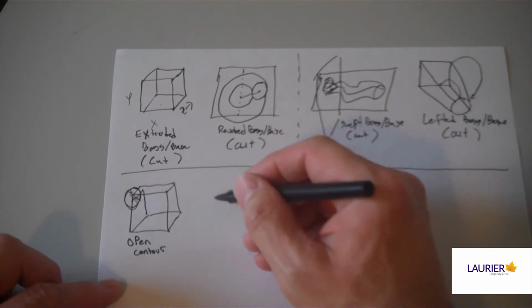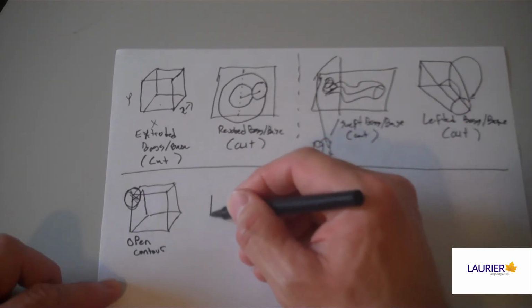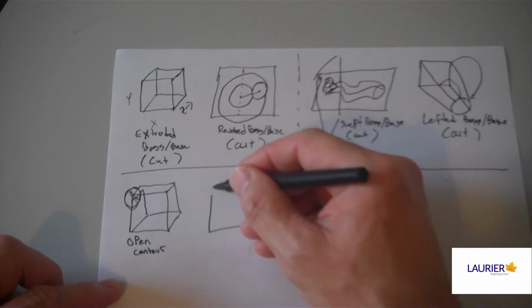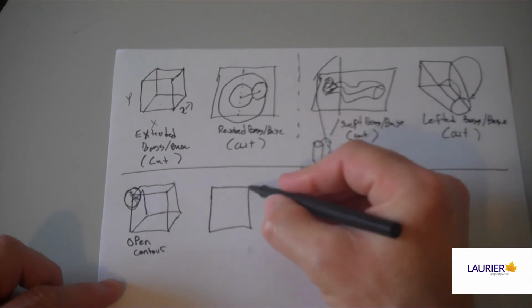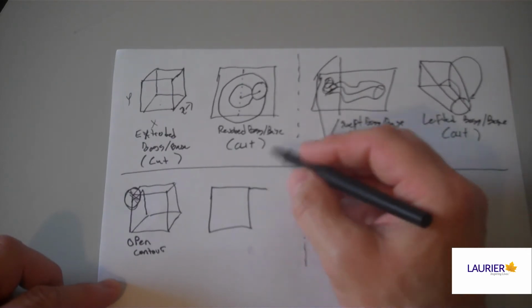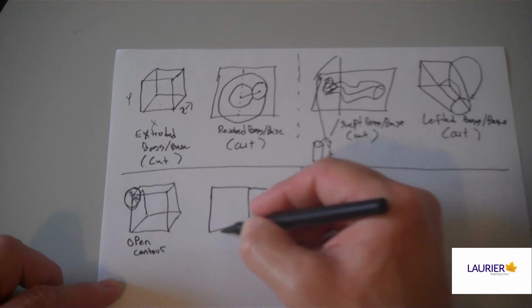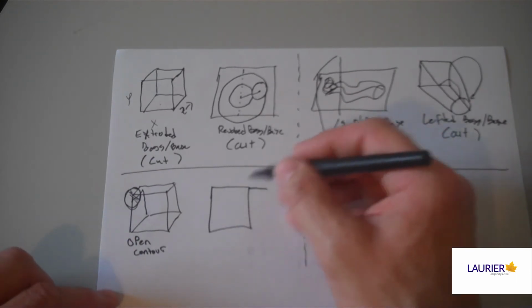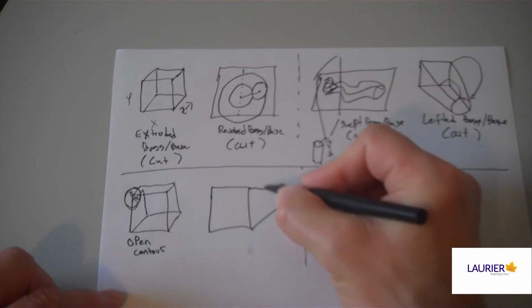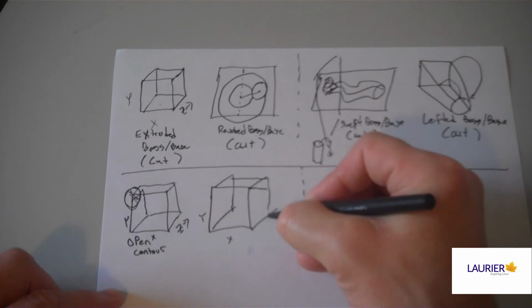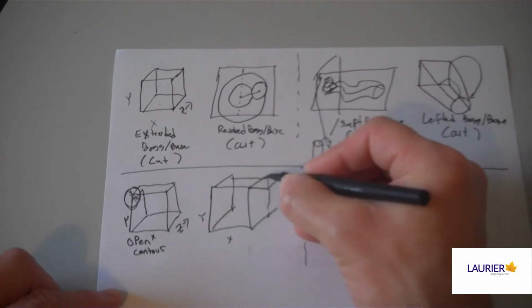The next type of error we're going to talk about is also a problem where part of the drawing does not have a volume when extruded. It's also the error with the funniest name. In this case, we've got our square, but it's got an extra line hanging off it here. We've got our closed contour. It's nice, it's closed, it's not the prettiest square ever, but it does capture an area. But then when we sweep this along the z-axis, we get this shape. Right, we get our cube, it's fine, but we also get this little wall hanging off here.